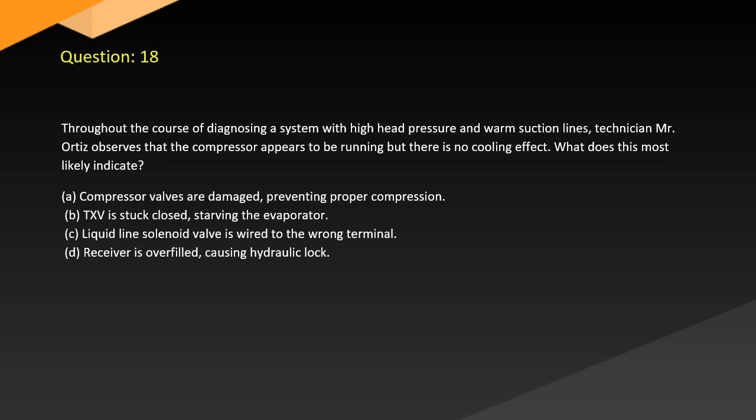Question 18. Throughout the course of diagnosing a system with high head pressure and warm suction lines, technician Ortiz observes that the compressor appears to be running but there is no cooling effect. What does this most likely indicate? A. Compressor valves are damaged, preventing proper compression. B. TXV is stuck closed, starving the evaporator. C. Liquid line solenoid valve is wired to the wrong terminal. D. Receiver is overfilled, causing hydraulic lock.